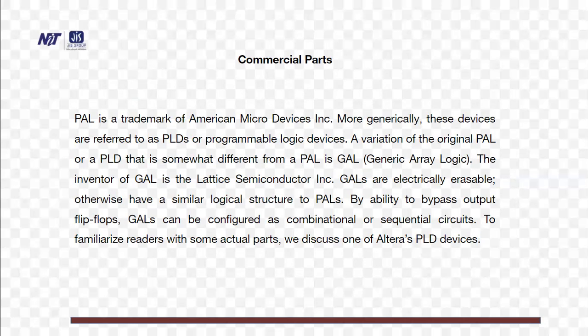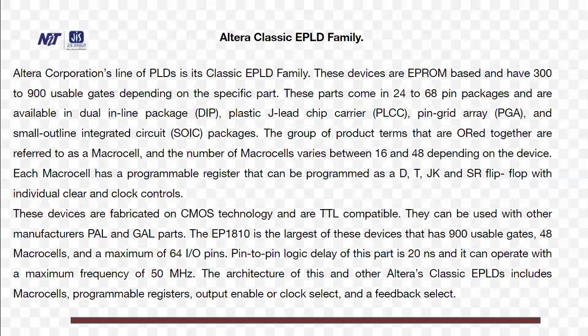To familiarize readers with some actual parts, we will discuss an Altera part. Altera Classic EPLD family. Altera Corporation's line of PLDs is its classic EPLD family. These devices are EEPROM based and have 300 to 900 usable gates depending on the specific part. These parts come in 24 to 68 pin packages and are available in dual inline package DIP, plastic J-lead chip carriers PLCC, pin grid array PGA, and small outline integrated circuit SOIC packages.